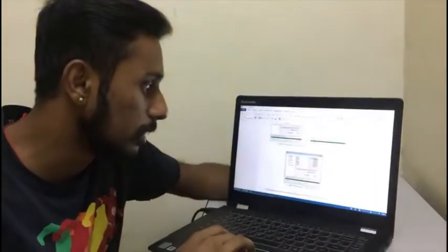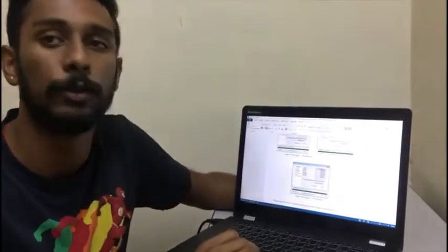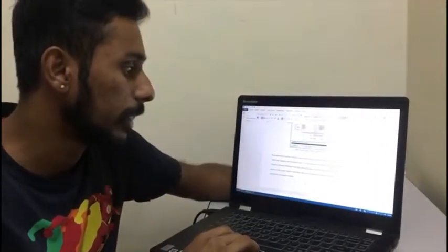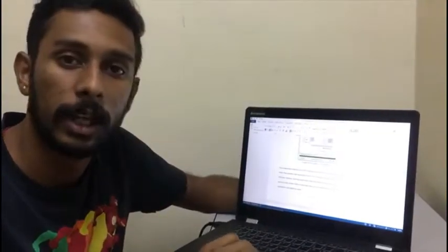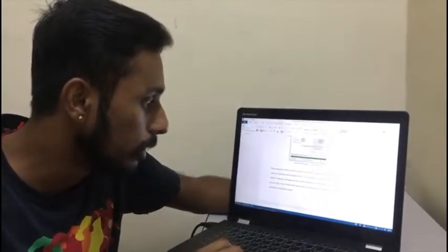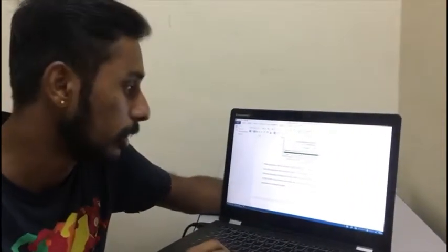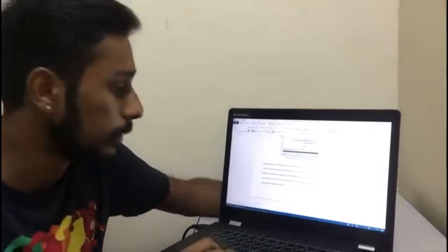So looking at the liquid waste from the V100 separator, the total from the liquid waste V100 separator is 1531196.42 kg per hour. Waste generated could be classified as 3 types, which is vapor waste from separator, liquid waste from separator, and top product from T101 distillation column. Main waste components are ethylene, methane, hydrogen, and water, where hydrogen could be reused for combustion process in the system, which would reduce the cost of production.